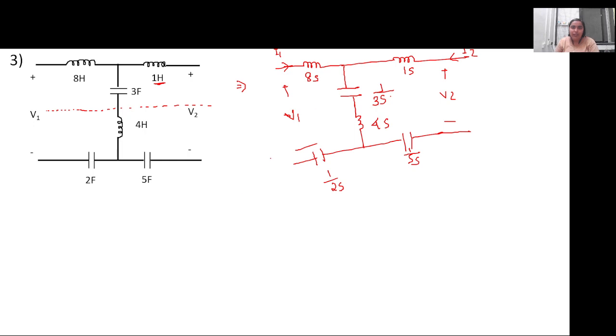Okay. So I1 current is flowing here, I2 current is flowing here. So the net current that will be flowing in this particular branch will be I1 plus I2. Since we are calculating the Z parameters, let us write the equation as V1 equal to some constant into I1 plus something into I2, right?